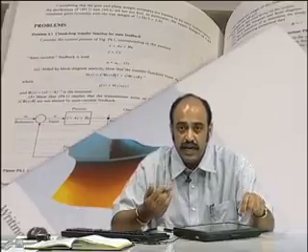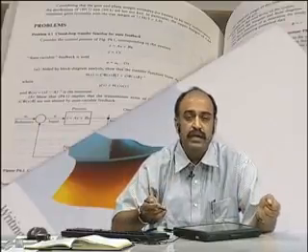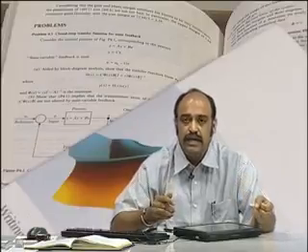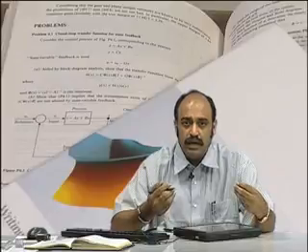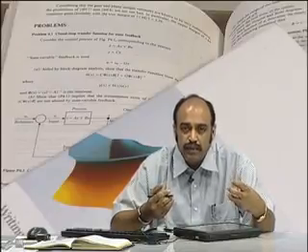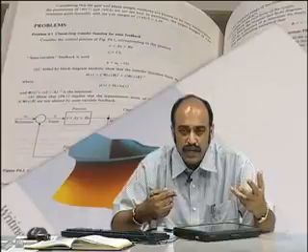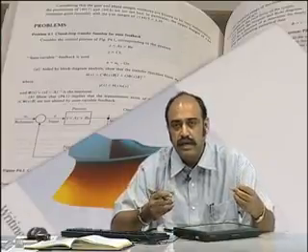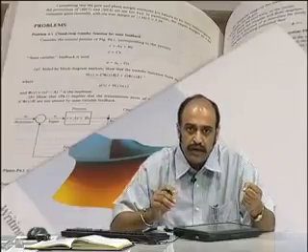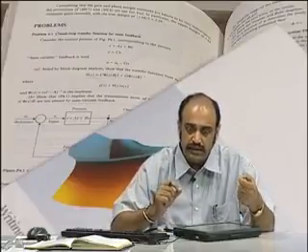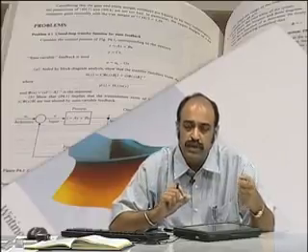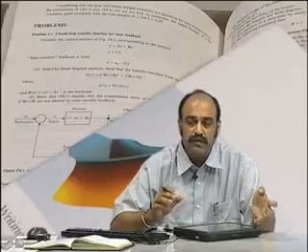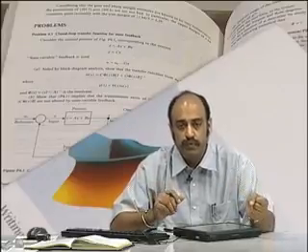The variation of the gain with frequency is not very evident in the time domain. The bandwidth is not so very evident in the time domain. The pattern of the pole 0, which will give you oscillation or that amount of damping, is much more easily understandable looking at the pole 0 plot. In fact, in the pole 0 plot you can position, this should be the damping, this should be the position of my poles, and work back and then evaluate what should be the value of LCs in the circuit, and that will be useful for design.